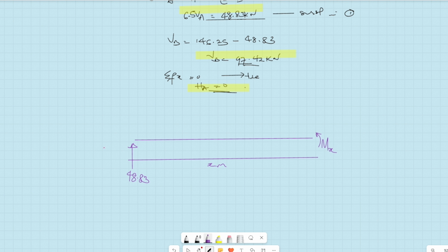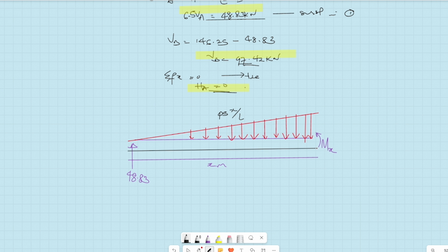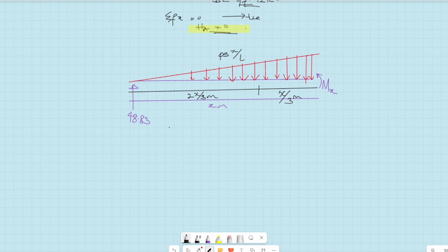So we want to get the different bending moment values along different positions in the beam. We have a triangular load on it. This load is acting at the point 45x over the length. And don't forget that we said it's acting 1/3 to this point. So this will be x over 3 meters. And when you subtract x over 3 from x, here will be what? 2x over 3 meters. So going forward, we need to determine a bending moment formula.